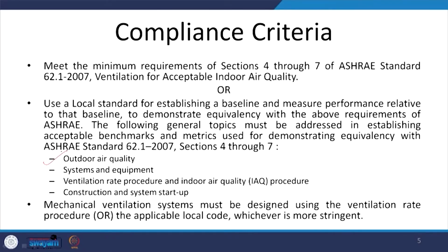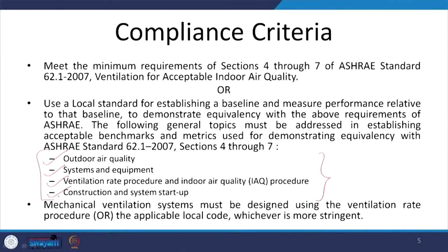One is the outdoor air quality which is being supplied. Second is systems and equipment. Next is the ventilation rate procedure and indoor air quality procedure, and then lastly construction and systems startup. When we are talking about all these 4, we are talking about the design of mechanical ventilation systems as per the applicable code, whichever is more stringent. So, it could be ASHRAE or it could also be the applicable local code, whichever is more stringent, but all these 4 will be taken into account.